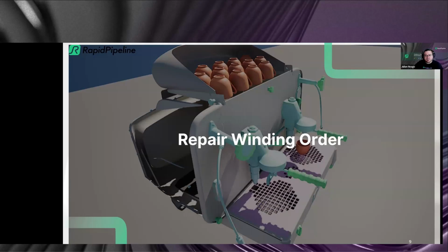Features like repairing winding orders are something we do on top of the tessellation, on top of just the CAD conversion. We have quite a few features dealing with bad geometry, bad winding order, flipped normals, and so on. So we have cleanup operations handling that. And on the automation side, these can all be ingested together into the CAD import directly, so you can make sure, within the batch processing for example, that you always correct the winding order.